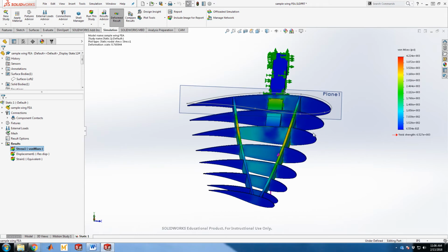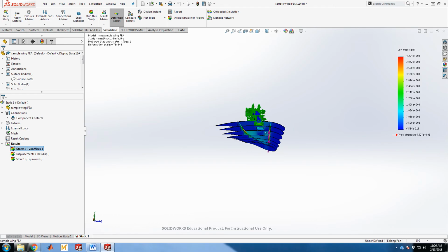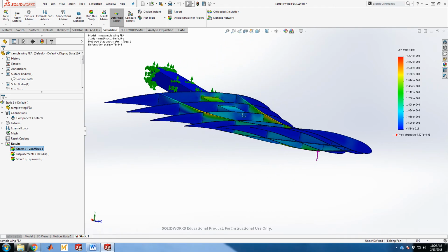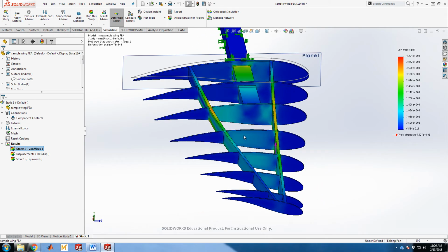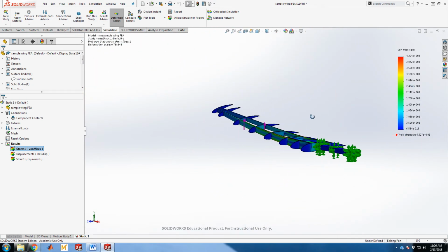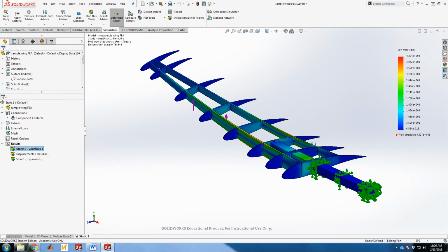That means you don't want to make those parts out of aluminum. You don't want to put a lot of your high weight, high cost materials there. But you see that the shear that arises inside of these central box sections of the wing can be significant. Now, keep in mind this is von Mises stress. You can read up on that on your own real quick, or you can wait till we get to that description in class. But this should be a sufficient crash course in how to use FEA to better understand stress flow